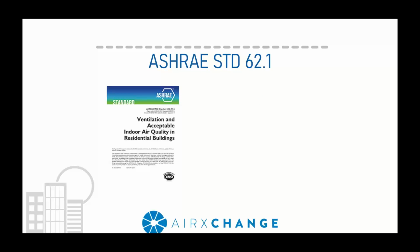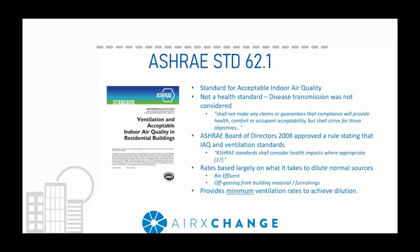So what determines the ventilation rate in commercial buildings? ASHRAE Standard 62 is the ventilation standard for acceptable indoor air quality in commercial buildings, and it's the most referenced standard in commercial building codes. I should state that the standard is not a health standard, meaning that disease transmission was not considered when developing the rates. It strives to provide guidance that provides health and occupant comfort, but it doesn't guarantee it. More recently, the ASHRAE Board of Directors approved a rule stating that ASHRAE standards shall consider health impacts where appropriate.